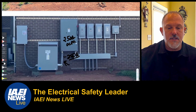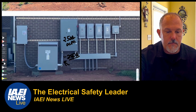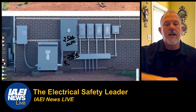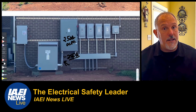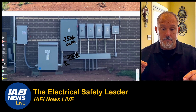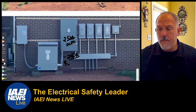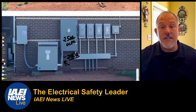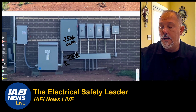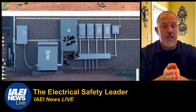B is inside nearest the point of entrance of conductors. We don't have to worry about that because we're outside. And C says where installed in accordance with 230.6 nearest the point of entrance of the conductors, and we don't have to worry about that one either. So since we're outside conductors, there's no length limitation. That secondary fusible disconnect switch did not have to be directly next to the transformer. It could have been down the way because it's all outside. So we meet the requirements of the outside secondary conductors.